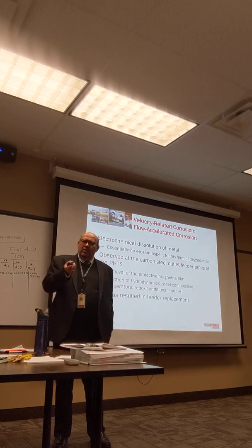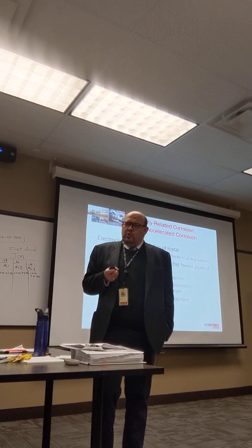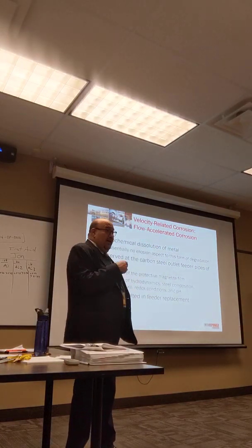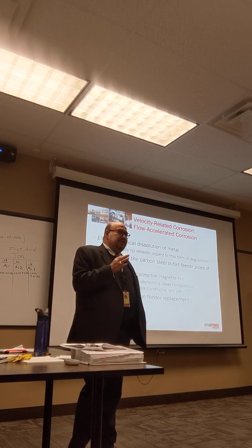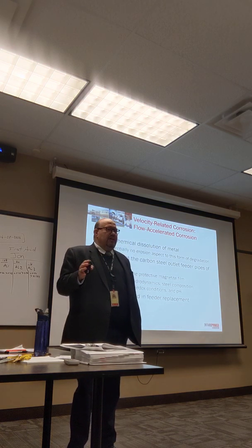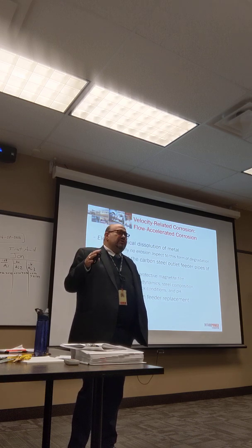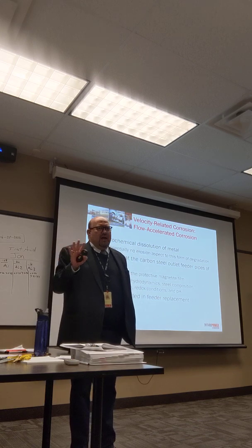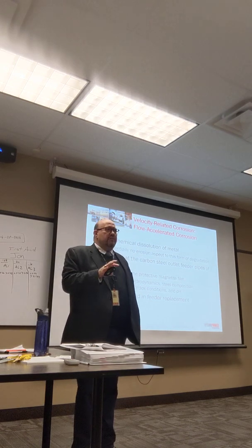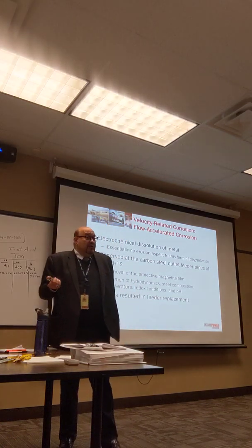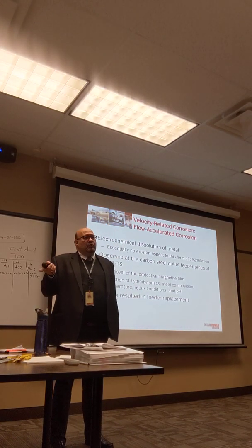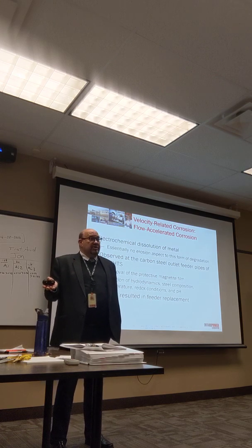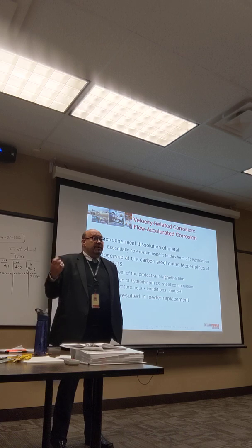We've also done something, Anil, with this one. I think they changed the material. It includes a little bit of chromium. That's right. They increased this in feeders. It's carbon steel A106 grade B, which is the lowest grade of carbon steels. Nothing special about it, just regular plain carbon steel, and it worked fine. The fact that we were doing all this engineering and trying to understand what's going on was actually a good decision 40, 50 years ago, because it worked fine.